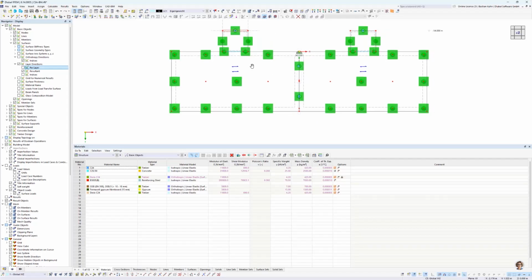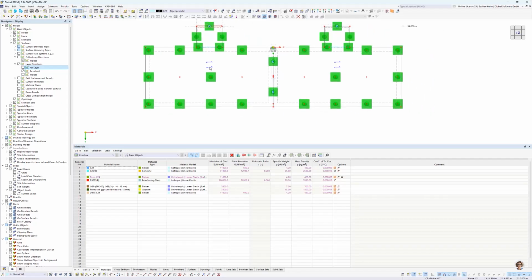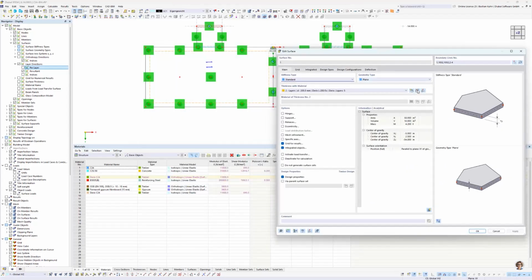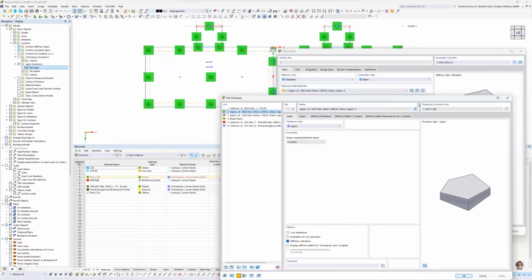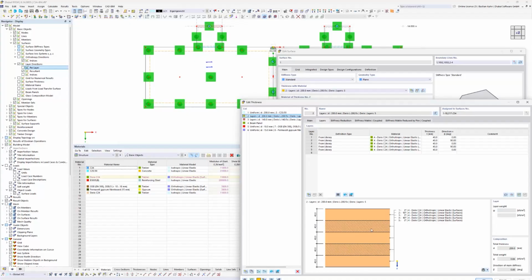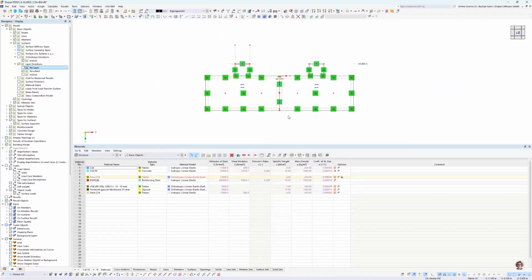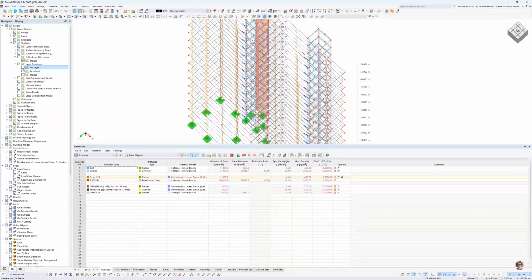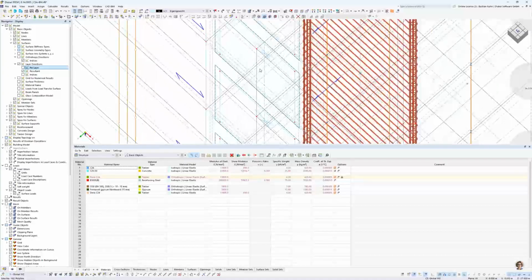And so you see that this is, if we imagine that there is the column here, wrong from the stiffness orientation. We have to take a more detailed look into it. You see that the layers are oriented with the top and bottom plate, which gives you the main stiffness direction in global X. And that's wrong, because you don't want to orient it that way. And we also need to look at the walls. They are also oriented wrong in here.